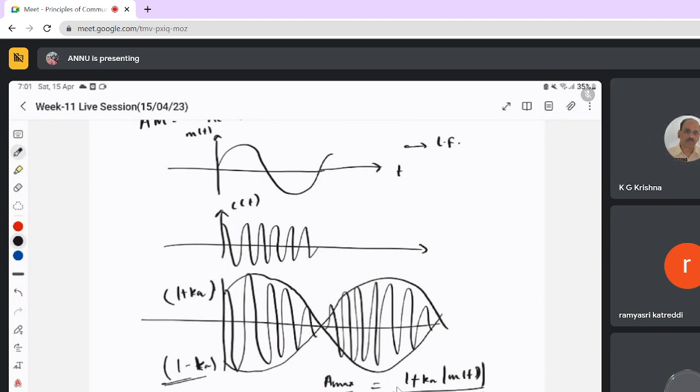Whenever the noise part comes into the picture, noise is directly proportional to frequency. My question is, for this traditional AM modulation used in broadcast radio, why are they using it? They can use simply SSB, saving a lot of power. Yes, saving a lot of power, but SSB requires filters, filter design. SSB is used exclusively for voice.